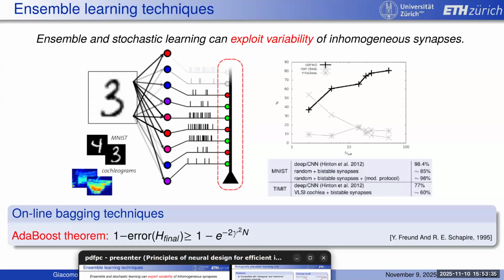And learning, I mentioned, is the other way to remove noise. You learn away the device mismatch. We have implemented several learning circuits throughout the years, including STDP. But there are many from theoretical physicists like Stefano Fusi, Nicola Brunel, and Christian Martins. Because they're biologically plausible, they're really easy to do in circuits, with just a few transistors. Once you convert any input signal into spikes, for example with pulse frequency modulation, you can send these spikes into the learning synapses.